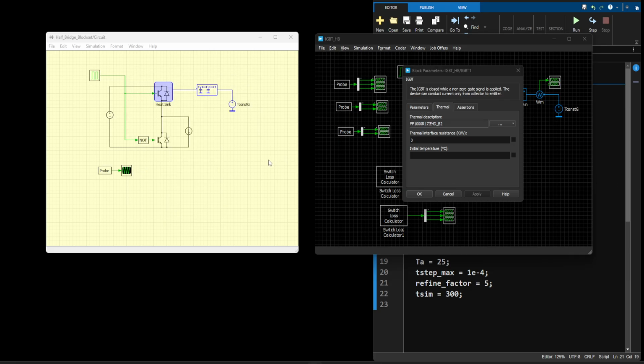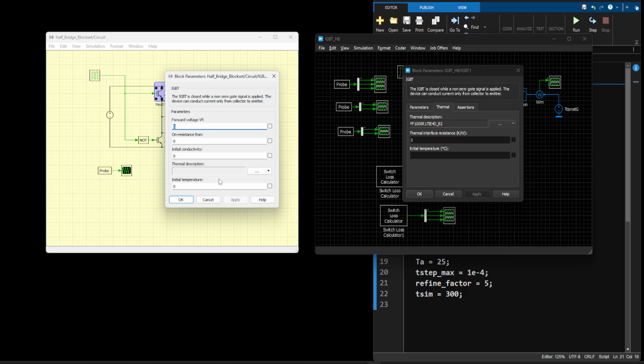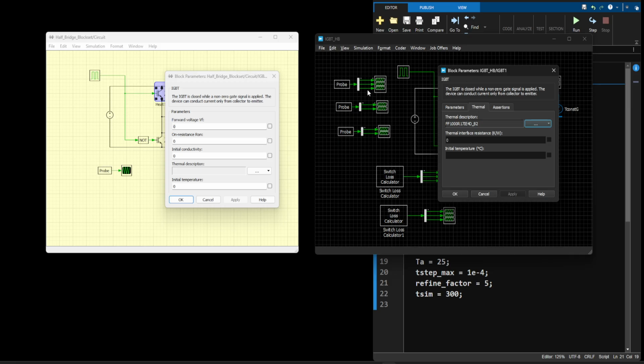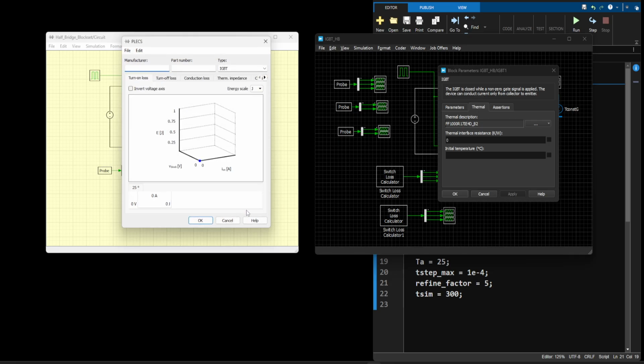There are two options that I know at this point of recording this video. Either we can describe it completely new, or we adjust the newer version of the XML file to that version of PLECS. To do that, let's start with the new thermal description. So at this point, I cannot select any of them. I deleted even the older version of XML. So let's include a new thermal description.